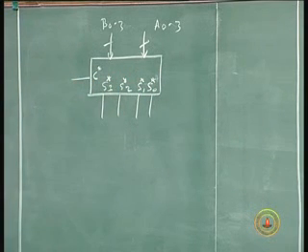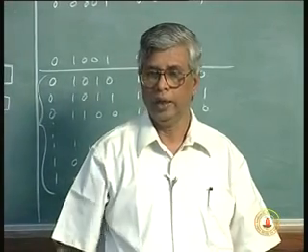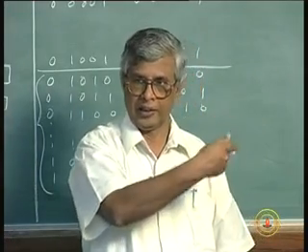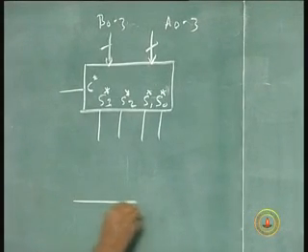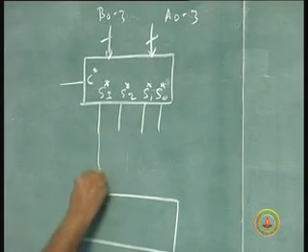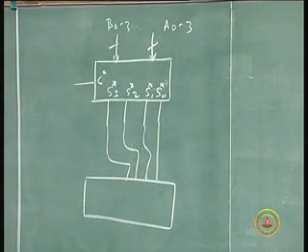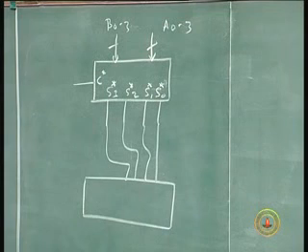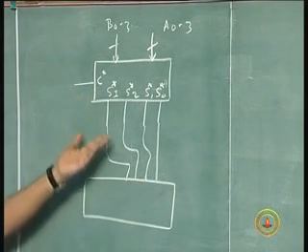So you need a 5-bit adder. No, I'm going to have one more adder. Add 6. I need to add a 6 to that, right? Let me explain. Let me first draw the circuit and explain to you. So this will be added with another adder in which we'll give this. To that I have to add 6. Because this is 4 bits, this 6 has to be added, so this is a 4-bit adder. So 2 4-bit adders instead of a 5-bit adder.